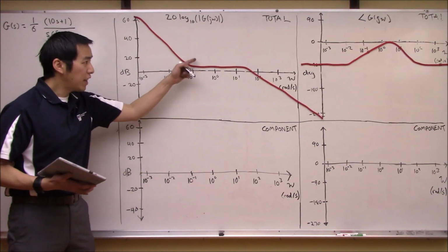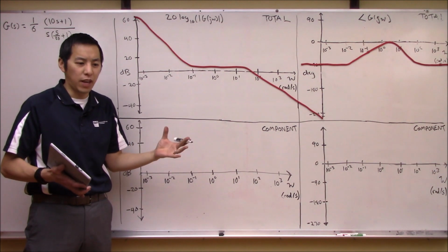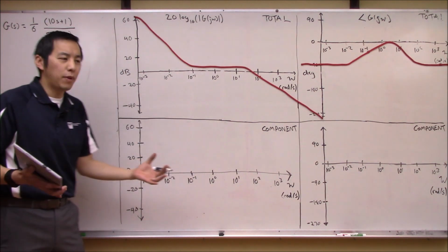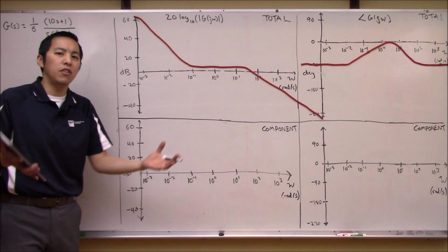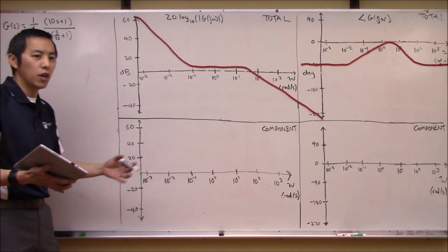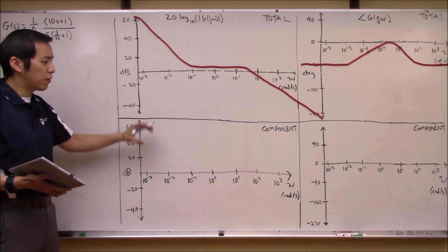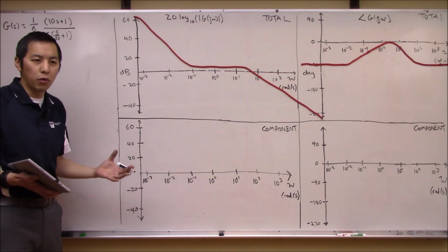Okay, so we validated that our sketch of our complex Bode plot is fairly accurate. And what I wanted to talk about now is a little bit of a teaser into the concept of loop shaping, or frequency domain shaping. Because now, hopefully, you can see that we can affect the Bode plot of a system by looking at how the individual components contribute.